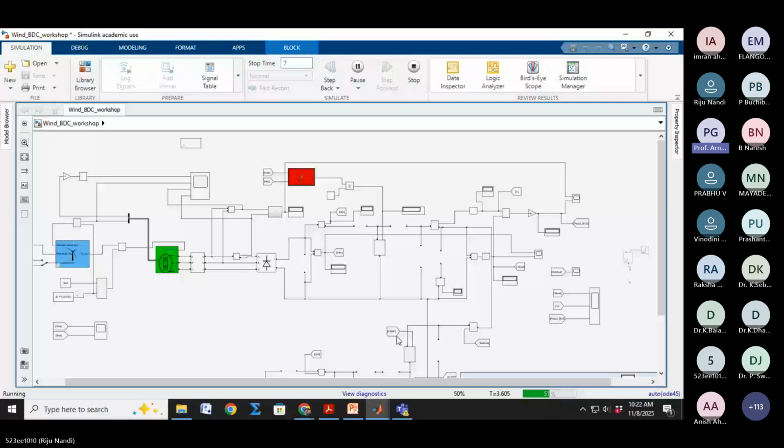Small signal modeling is normally done for linearizing the converter, for designing the classical controller. Basically, we showcase controllers like the PID controller, and sometimes lead type controllers, based on the merits of the converter dynamics.